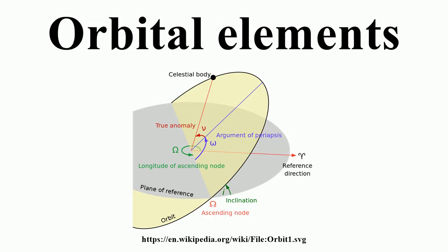Keplerian elements can often be used to produce useful predictions at times near the epoch. Alternatively, real trajectories can be modeled as a sequence of Keplerian orbits that osculate the real trajectory. They can also be described by the so-called planetary equations, differential equations which come in different forms developed by Lagrange, Gauss, Delaunay, Poincaré, or Hill.